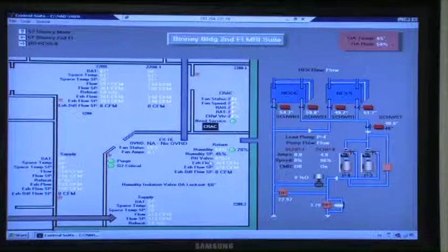How are we verifying that it actually is going to flash into a steam form coming out? That's something that I'd be concerned about. We're going to find out soon enough, but it looks like we have enough equipment to go by, if it does happen, to say okay, command that, override that lockout all the time open. Don't use it. It'd be no different than if the humidifier wasn't calling. Exactly. You're in the same position.